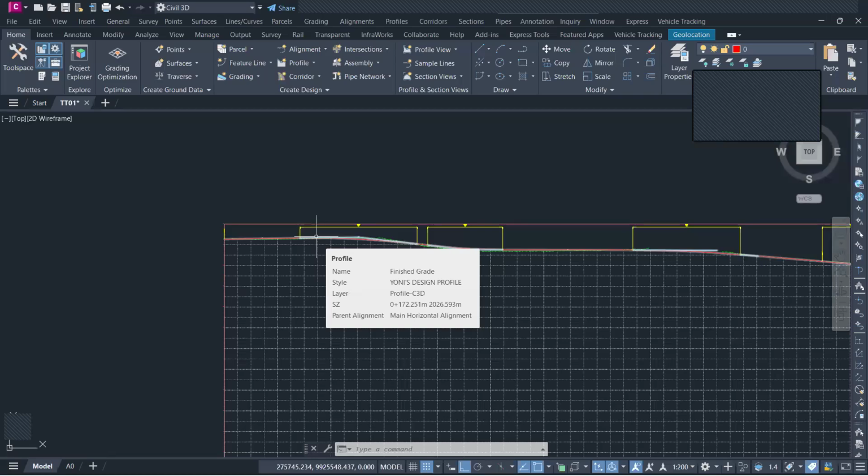As the excavation is going, we always say it is good to position your benchmarks or beacons outside the road corridor, somewhere that, even with the vibration of the machines during compaction and all of this site movement, they are not going to be affected. Because even 2 millimeters, 2 centimeters, 10 centimeters is going to affect the final output, and most importantly, the quantities of your project.